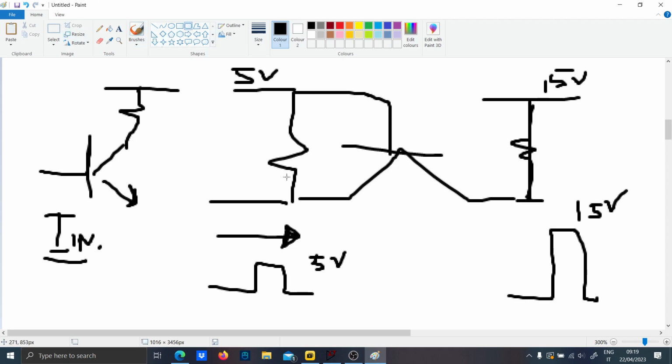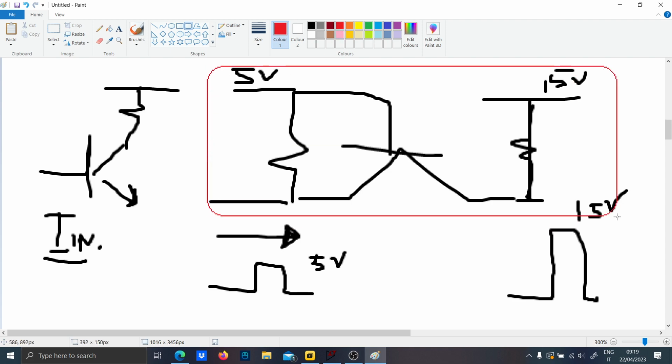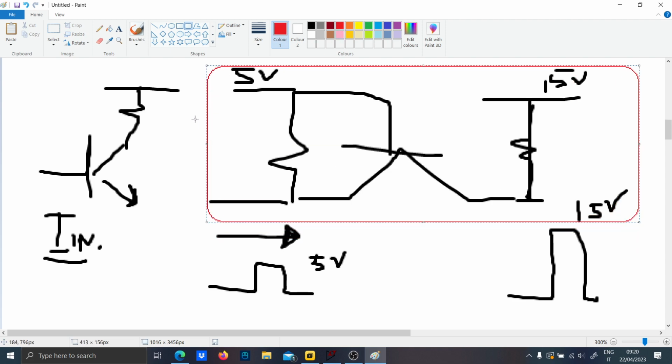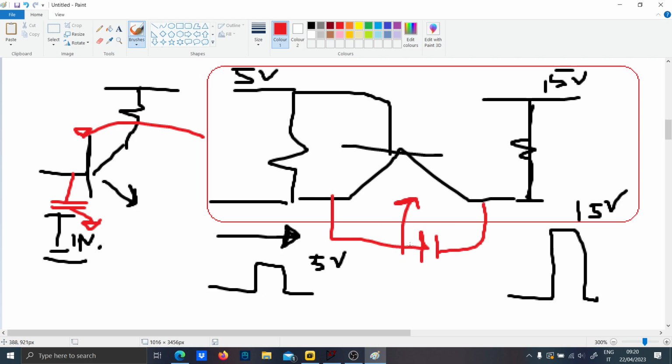The common gate solution, the non-inverting solution, is the most adopted, and maybe I will try to use it later. For now, let's use the inverting solution, which requires just one power supply, and it is the fastest and the easiest way to simulate in LTSpice. By the way, this circuit here is faster, dynamically speaking, with respect to this, just because of the parasitic capacitance that the signal is gonna see. You're gonna see this parasitic capacitance here, but here instead you have just this parasitic capacitance, which does not affect the dynamics so much.